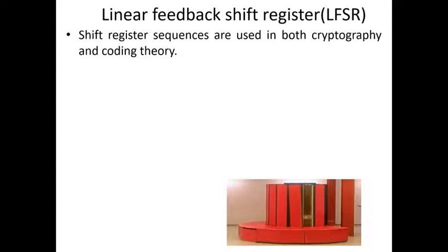You have used a shift register and the flip-flops are separated in between with XOR gates to determine the next state, and so on. And there is always feedback coming in the form of an AND gate, and from that there is feedback coming to different points, the different modulo 2 adders. So whatever you did with cyclic code encoder and decoder, they are the simplest examples of LFSRs.